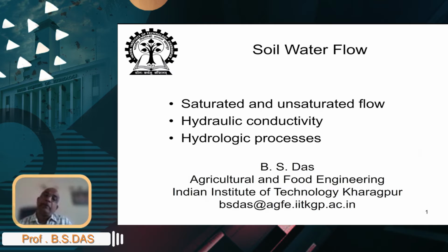So with this sort of background that we have built, describing water relationships at a static equilibrium, right? We talked about water retention characteristics. Every point in a water retention curve, we discussed that each point, whether it is field capacity, whether it's permanent wilting point, or any of those static soil wetness levels, is linked to its corresponding equilibrium state or static energy content. So that's the concept of water retention characteristics, the relationship between how much water is held and how much energy is involved in holding that water in soil. So these issues that we have discussed pretty much look at the static behavior of water in soil.